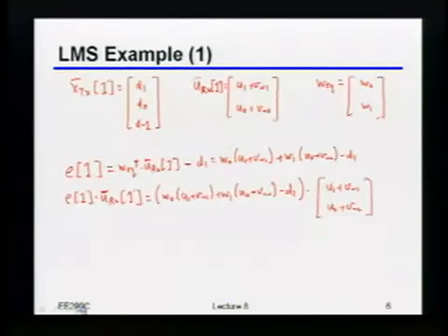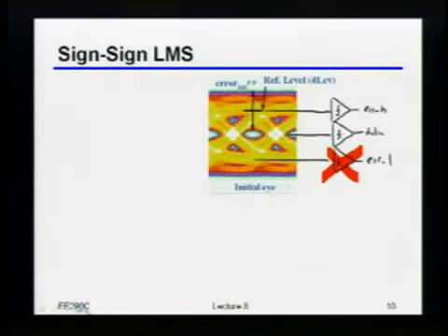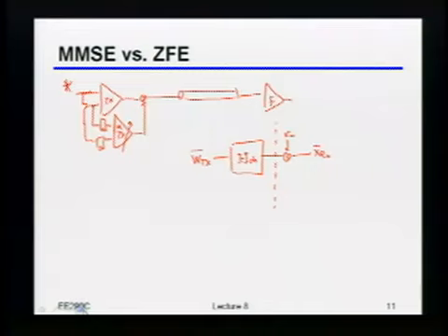So the practical issue here is that you don't actually have the input available to you to check what the noise going into the equalizer was, so that you could tune the equalizer based on how much noise was actually going into it. In other words, if I want to measure some error signal here, the only error signal I have available to measure against is the analog input into the receiver, after the equalizer, and then just compare that to my ideal transmitted data.